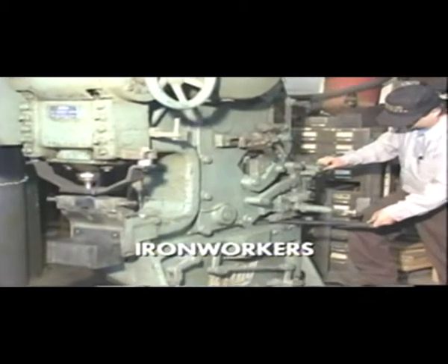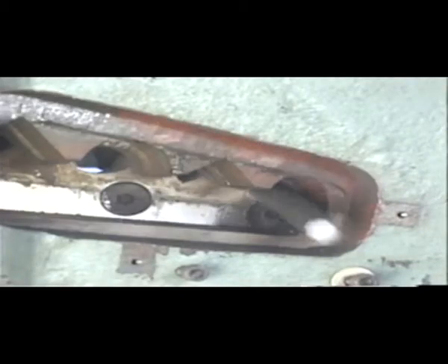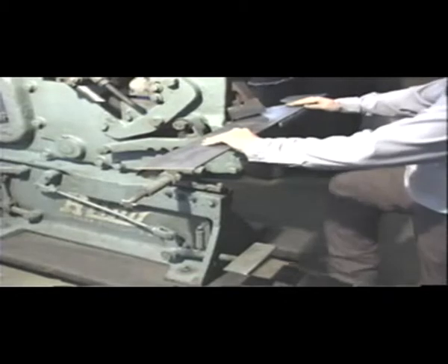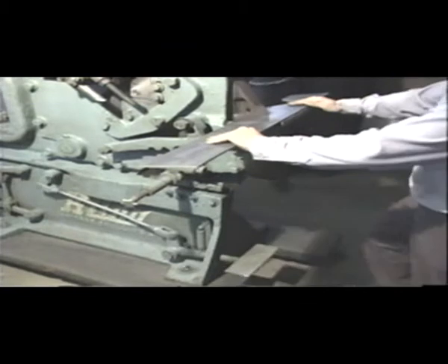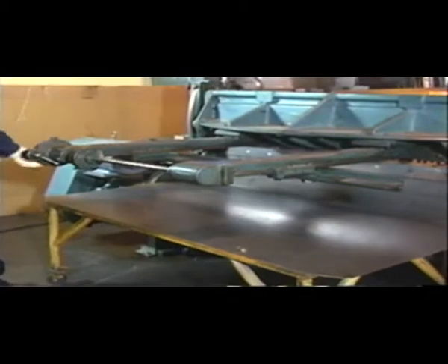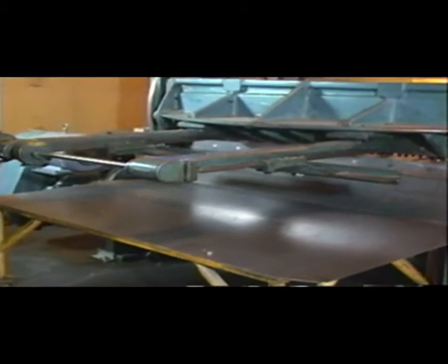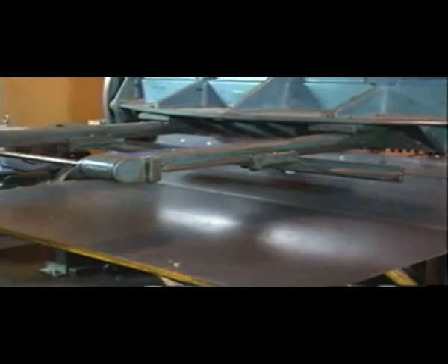Iron workers perform shearing of plate, structural shapes, and bar stock, as well as several other operations, including notching and punching. Shears must have some kind of gauge for measuring the part to be sheared. Four primary methods of gauging include back gauging, front gauging, squaring arm gauging, and programmable gauging that can operate under computer numerical control.